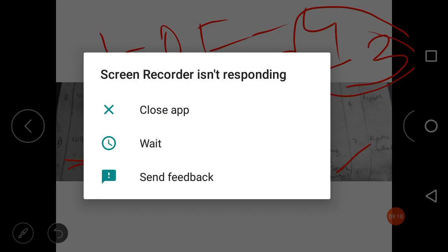And then the addressing mode. Here the operand's address is indirectly mentioned in the instruction. Again I am repeating, the operand's address is indirectly mentioned by the register pair. So the addressing mode of this type of instruction is register indirect addressing mode.